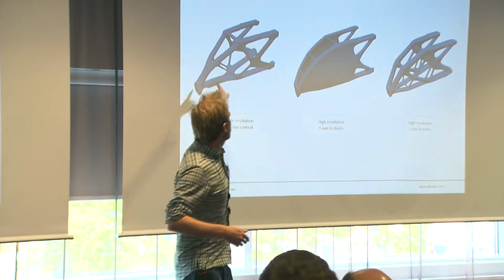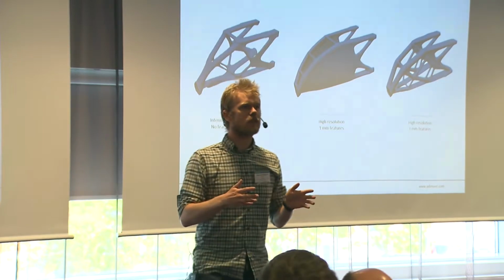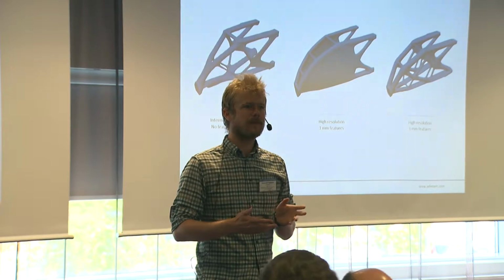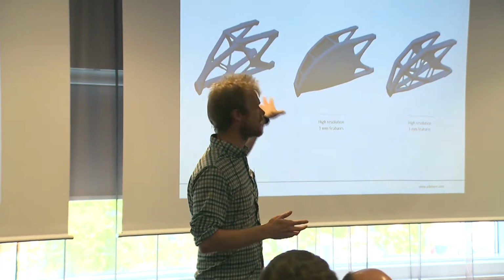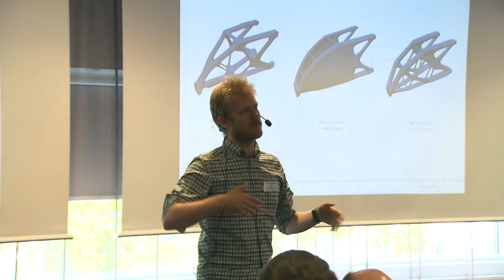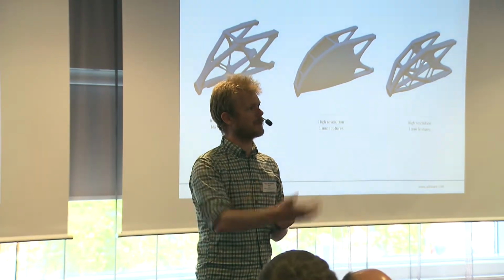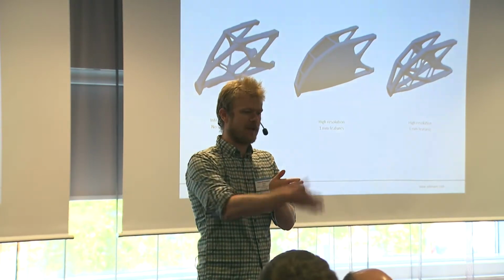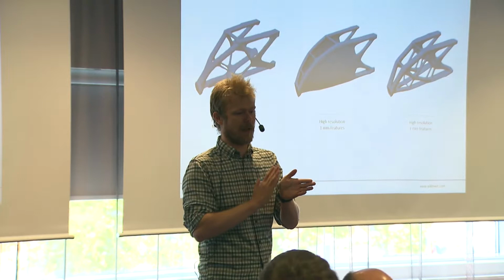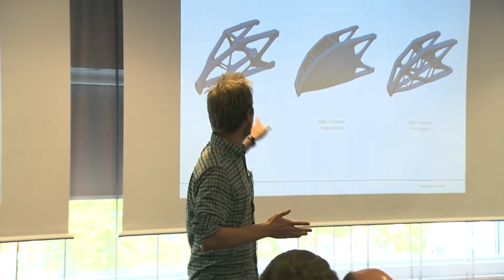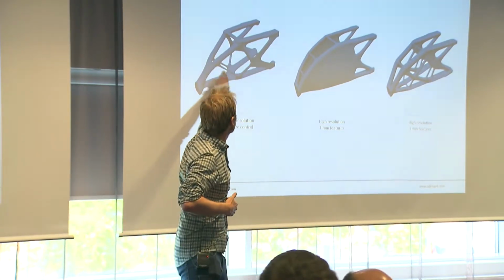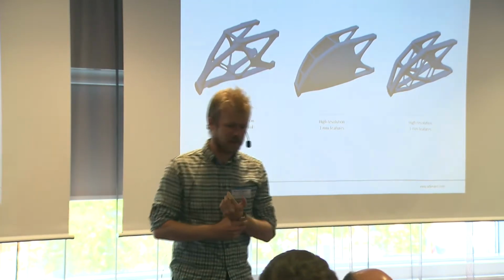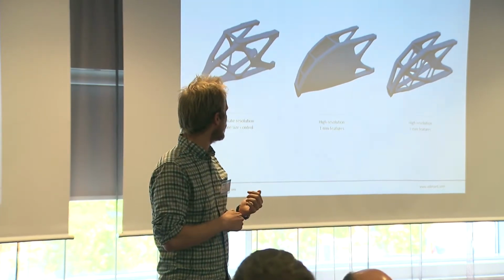First of all, a lot of these rods have disappeared and turned into walls. And this is actually a bit surprising for most people, that this is a fundamental change in the design. But when you use your intuition and think about how forces are distributed, if you have several load cases, then a wall is able to carry forces in different directions, where a rod is only really good at transferring forces along the direction of the rods. So here we are taking much better advantage of the material in the design.